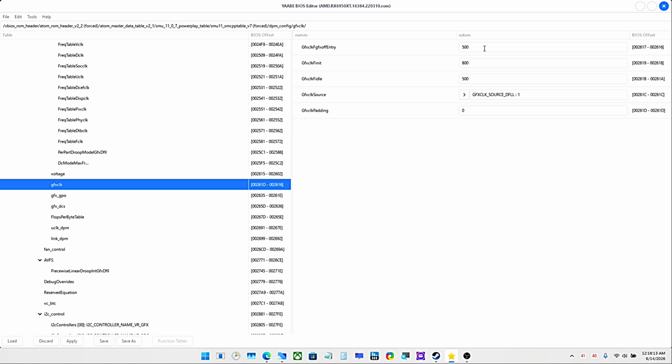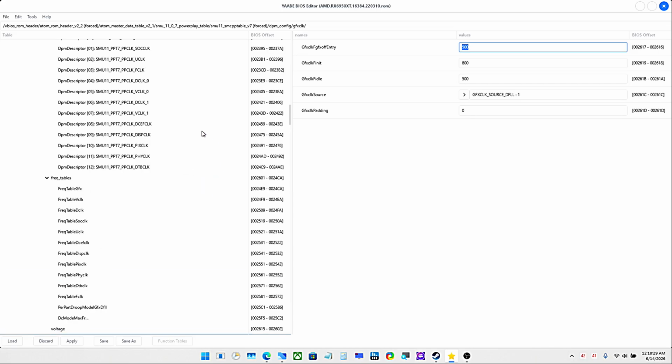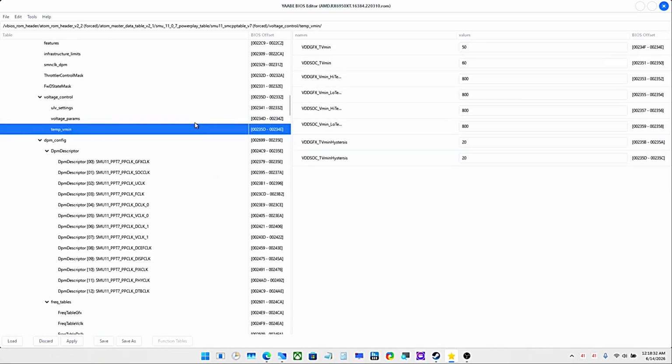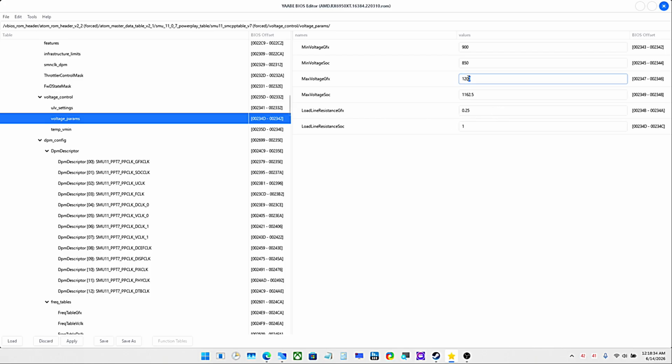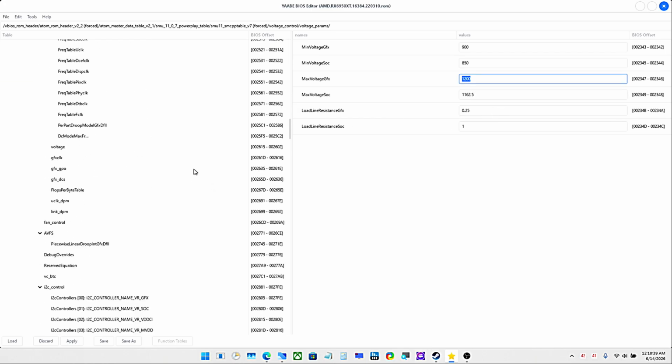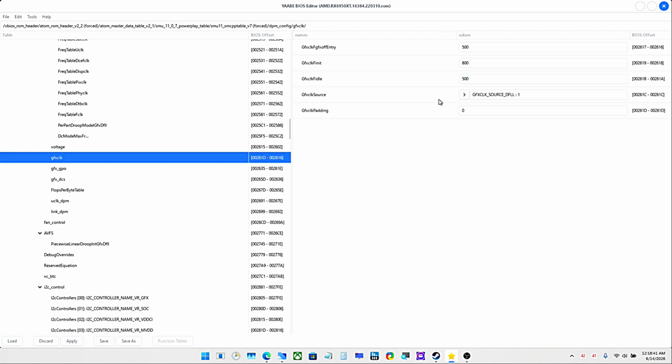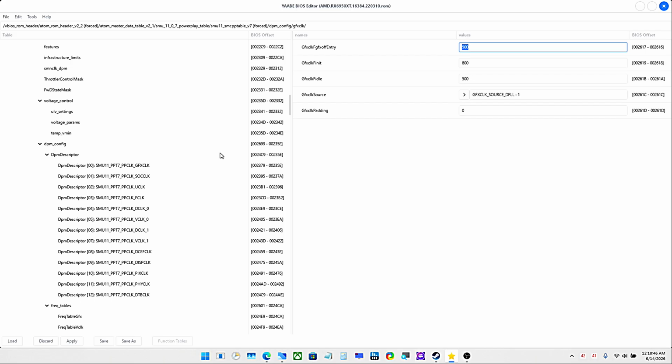But you have to be very, very careful to set this frequency here on all 3 of these to a frequency at which you are damn well certain that the voltage at which you set up here and voltage per amps, make sure that that's 1200. You know that this frequency you're going to set here is stable at that voltage, very stable.